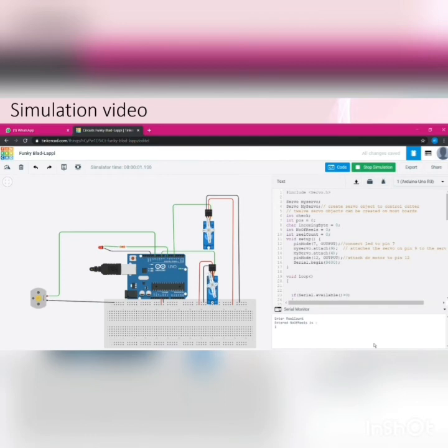Servo motor 1 will move between 40 to 60 degrees, which will help the thread move in a uniform way. This servo motor ensures that the thread moves in a uniform direction to the reel side. The rotation of the reel will drag the silk thread from the spool successfully.